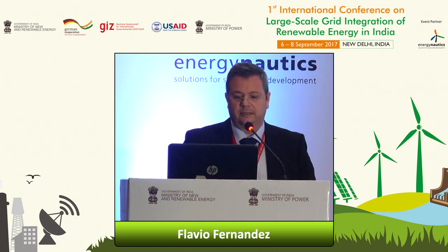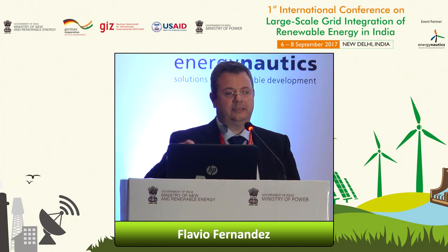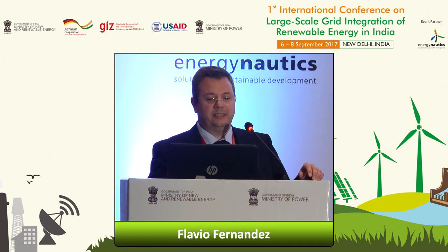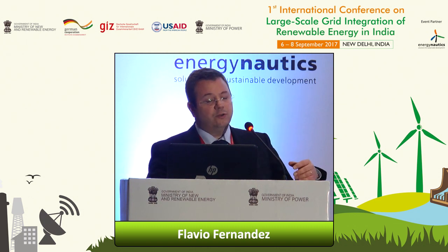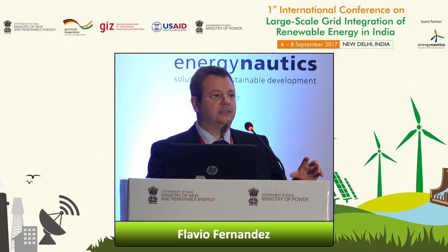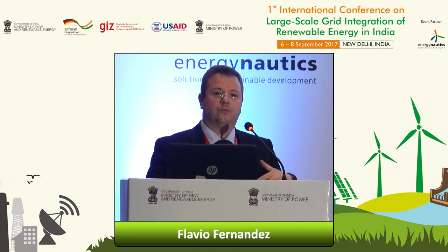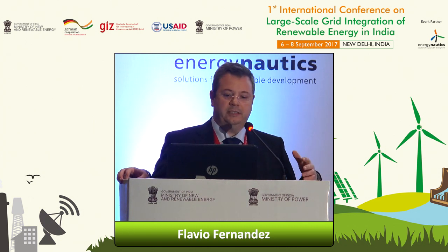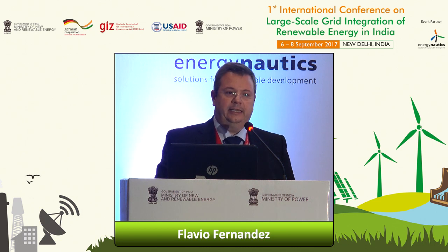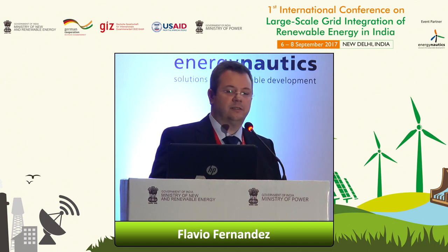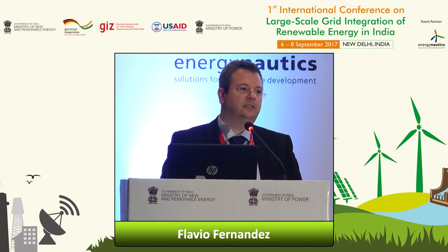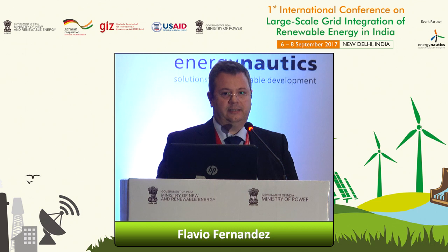And the other thing we should keep an eye on, and I think this could also be a good handover for the next presentation, is the fact that renewable generation is partially embedded in distribution systems. So if we want to model them, we need to account somehow for the distribution system or for this embedded generation, right? We are observing now in Germany the discussion that the dynamic performance of the embedded generation is getting more relevant for the stability of the system, also in terms of providing ancillary services, as we have seen in some other presentation.